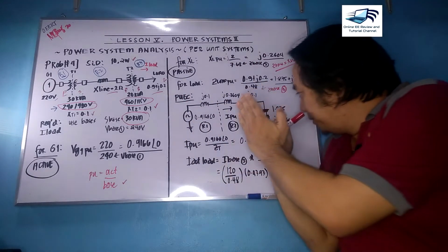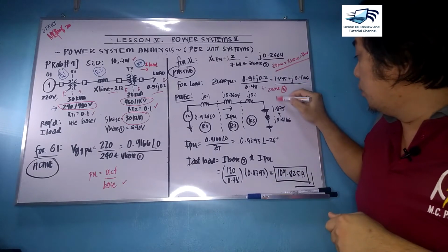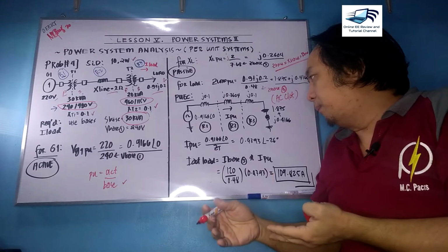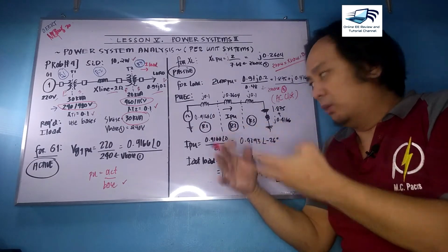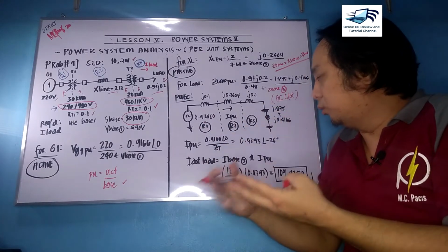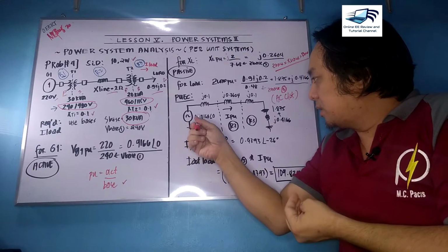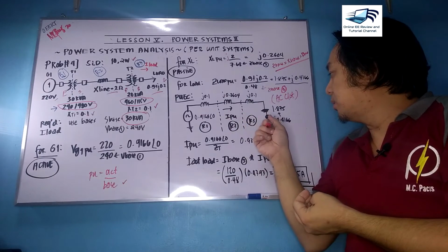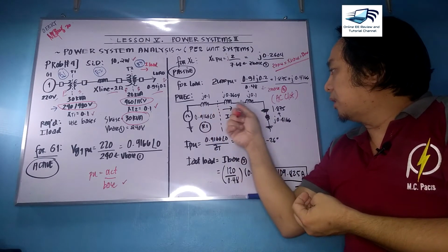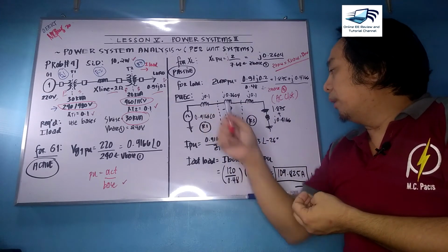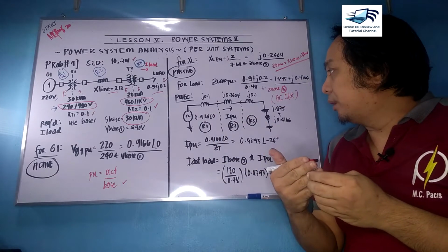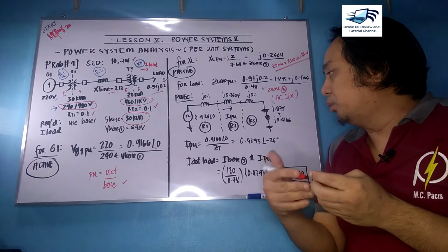Now we can proceed to the development of the per unit equivalent circuit, or PUEC, and we have this AC circuit. It is in terms of a per phase fashion. Since it is single phase, no harm done, you do not need to divide by square root of 3. So this is your generator voltage, this is your X line, this is your load, and these are the transformers T1 and T2 respectively, where we convert the reactive elements to the new base.